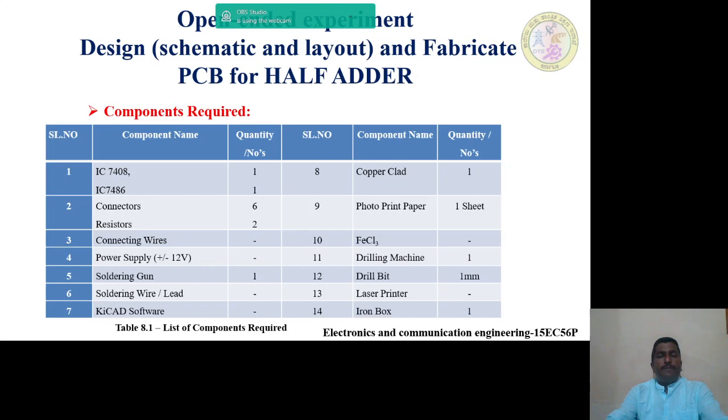For this experiment, the required components are IC 7408, IC 7486, AND gate and XOR gate, connectors and resistors, connecting wires, power supply, soldering gun, soldering wire, KiCad software for schematic layout and PCB layout design, copper clad, printed photo paper A4 size, ferric chloride FeCl3,